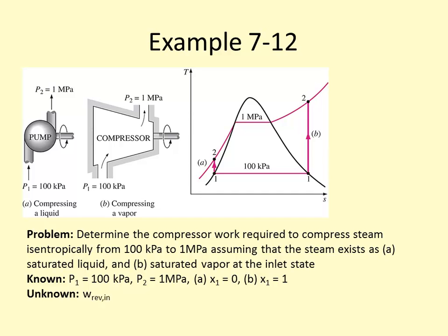So we don't have to account for kinetic energy. We're not told anything about velocities in this problem. If we were given that information, we may need to consider it, but generally with a pump, the velocities are so low and they don't change very much that it's not something we have to worry about. Sometimes with a compressor, the fluid will speed up, but usually not significantly. So again, in the absence of any information about velocity, we can't make any assumptions other than to assume it's negligible. And in most cases, even when we were given the velocities, it didn't add a very significant difference anyway.